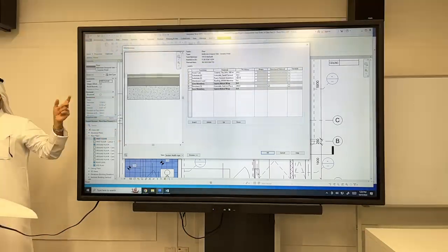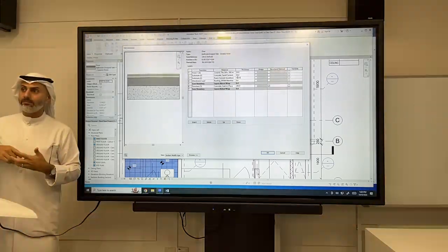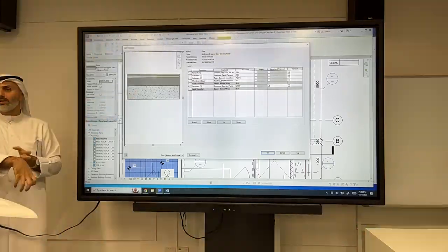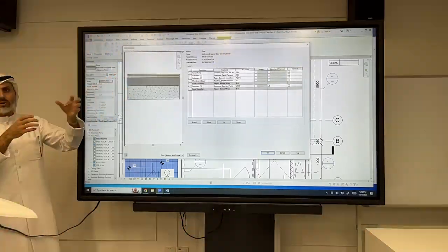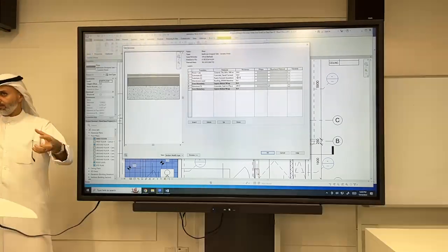One problem is, let's say 10, 20 years later you want to rearrange the toilet, the bathroom. Now there's an opening in the concrete, so you have to keep the toilet where it is. The way we do it in Kuwait, where we drop the slab, you can remove all the piping and move the bathroom, the toilet, anywhere else.